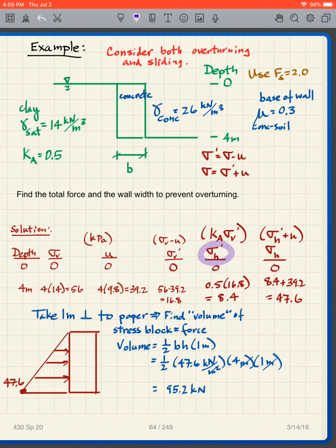Once this is built, then what happens? Then this wall moves outward. It's like putting up our bookend and then letting go. The wall moves outward, so I have Ka. I have active pressures. In other words, the wall is moving away from this soil. And that is why I get an active earth pressure there.